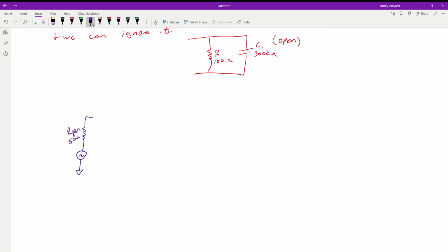So if we have something down in the 50, 60 ohms for our total impedance, absolutely that R_gen is going to steal half the power at 50 ohms of rest of the circuit impedance. But when our circuit impedance is up around 1,000, 2,000, 10,000, that 50 ohms can effectively be ignored because it's not going to create any major problems for us. But just realize that it is there and we do have to take it into account, just like the winding resistance of an inductor. That's another thing we have to take into consideration as well.